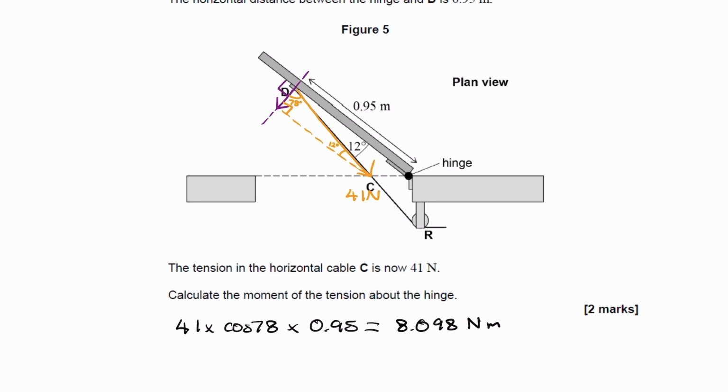So increasing that distance increases this quantity, but decreases this quantity. So we can't quite tell exactly what that would do for our moment. So I think the safer answers would be to increase the mass, therefore increasing the tension in this cable, or to pull the pulley further away from the door to increase the angle and therefore increase the component of tension perpendicular to the door.